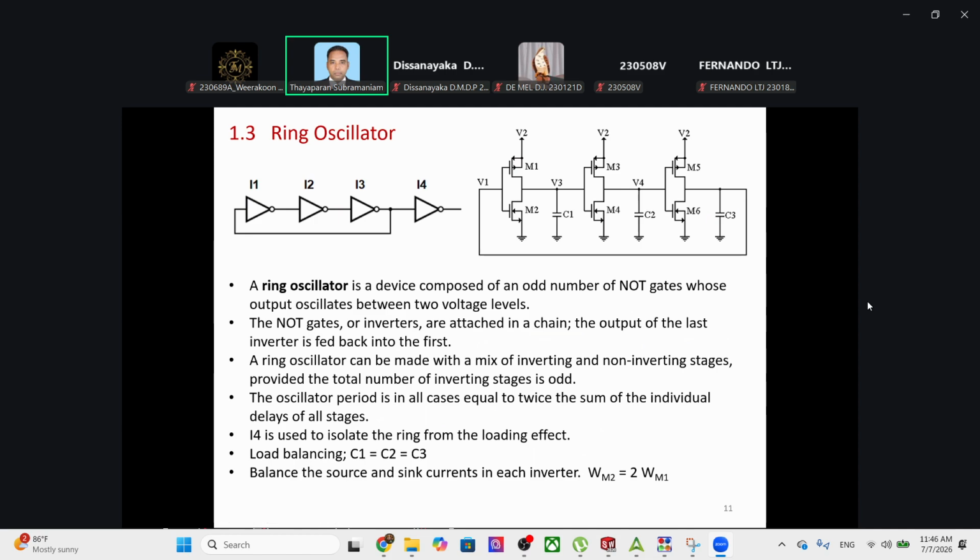The more delay gates that you put, the more propagation delay. More propagation delay means less frequency. Agree? Therefore, fewer elements. What's the minimum number of elements that we can have? Only one inverter. One inverter. So input is equal to output. This is oscillation, feedback.